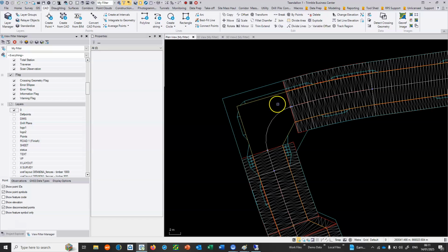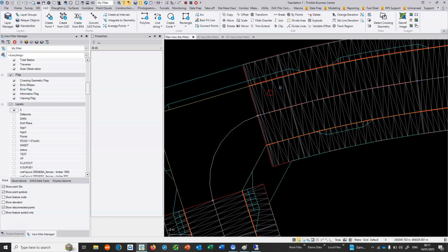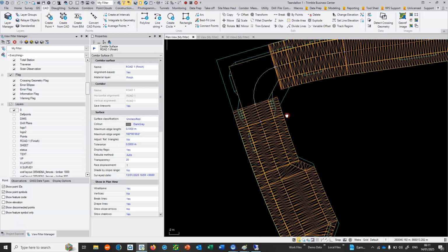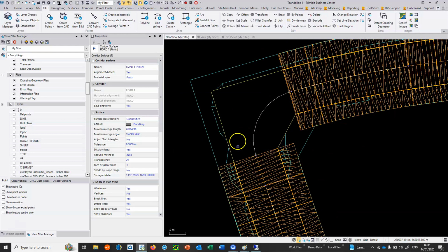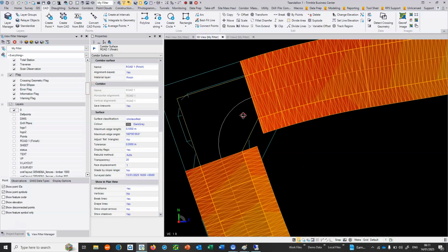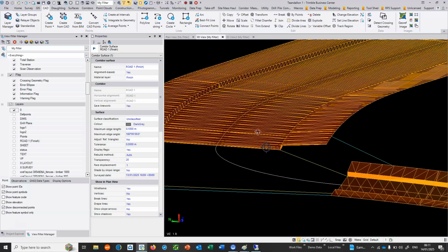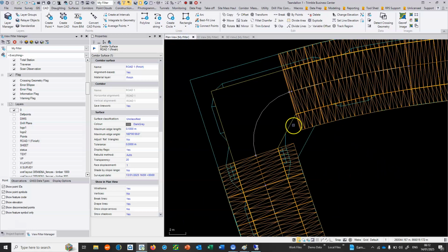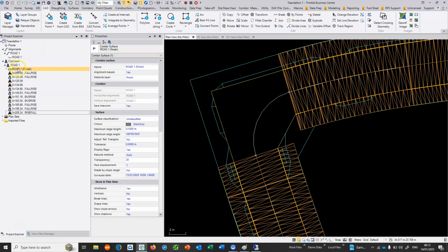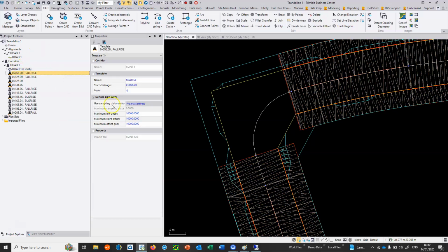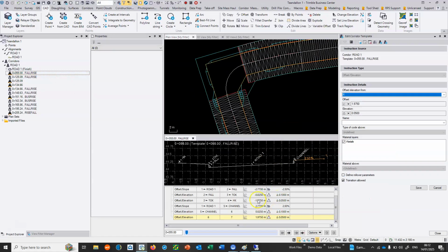So what we first of all have is the road design put in where it will model normally. So therefore we've got a good surface to work to. If we jump into the 3D view, we can see that we've got a good surface to work to there. And then I've gone in and edited that road and widened it very, very slightly to make sure that when we're draping on it, it's wide enough so we can actually drape onto it. So this width should be 275, and I've just widened it out to 277.